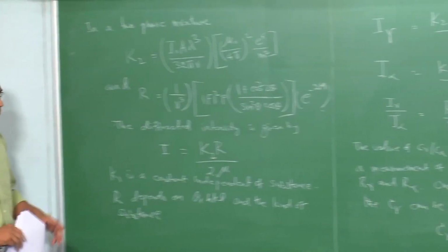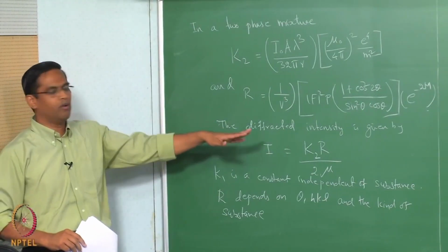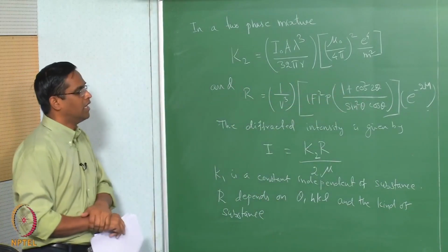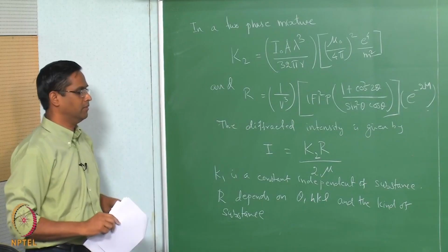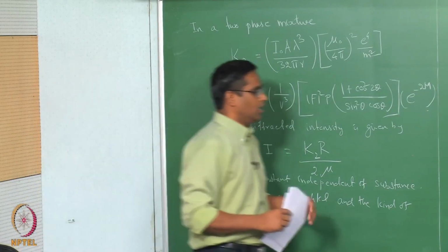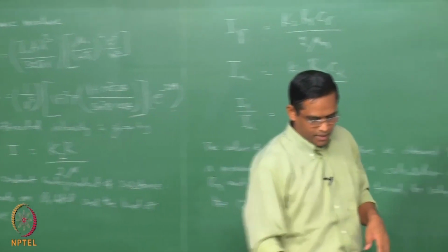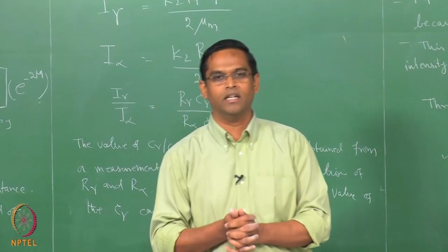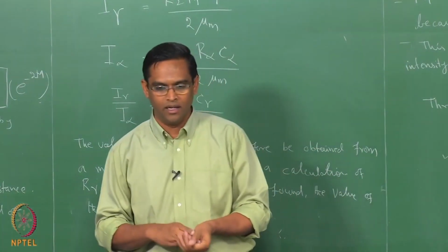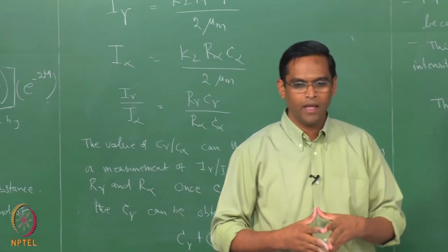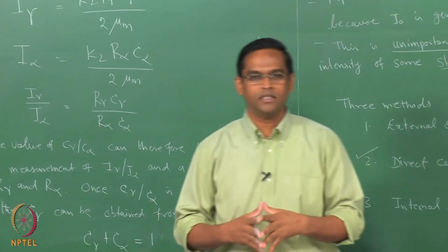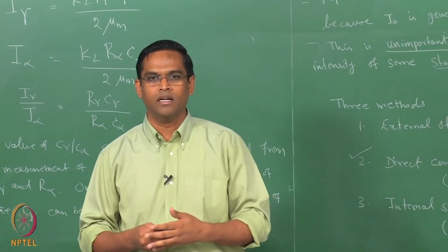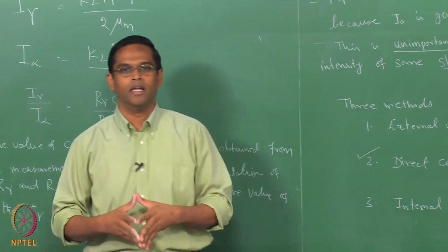So, even if you have one more phase, you can find this out from the direct comparison method. Like that, you can make use of the X-ray diffraction technique for identifying the phase and calculating the phase fraction. Another important application is stress measurements. I will again discuss the very basic principles of stress measurements in the next class.